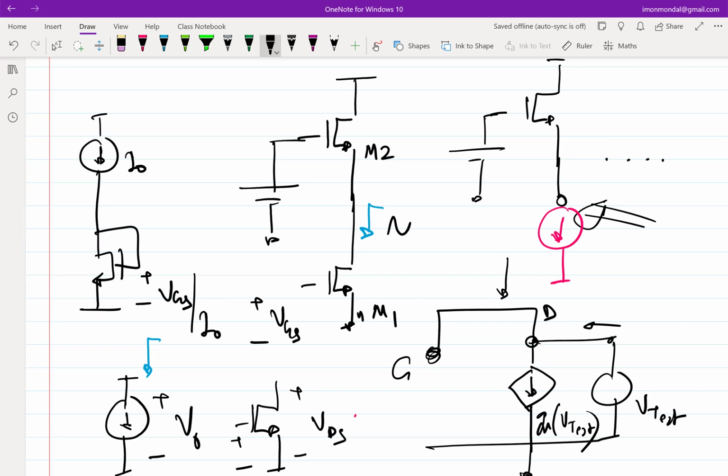Right? So now, the good thing again of integrated circuits is similar transistors which are placed very close by almost always have similar threshold voltages. If one changes, the other also changes. So for all practical purposes, you can assume that all these NMOSes are identical if they are sized identical.